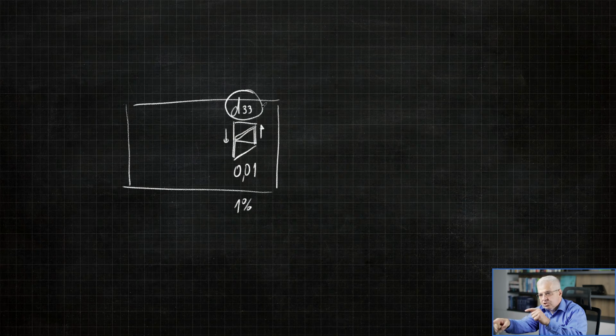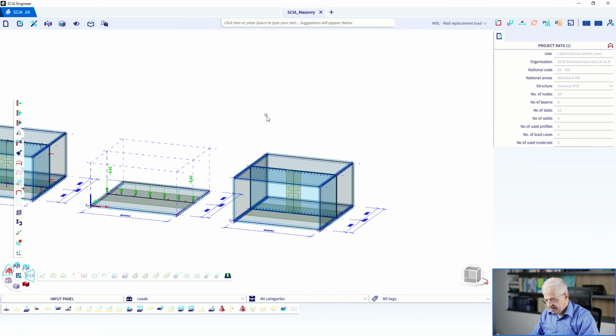This is a collision with our orthotropic properties which we want to introduce for the wall, and they will be overwritten, so we cannot use both in the same model. Therefore, this is not the right way for us.